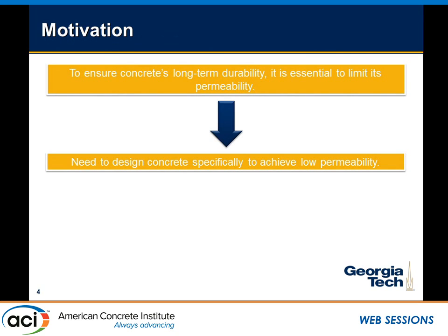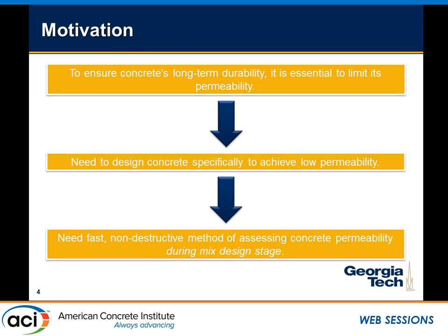Typically, at the mix design level, most of the tests that are commonly used take a while to do. Like a long-term diffusion test, for example, might take 90 or more days to conduct. And moreover, they provide just a snapshot of what's going on in the concrete. You're only looking at a particular age. What's more important is seeing how that changes over time. So we need a fast and non-destructive method of evaluating the permeability during the mix design stage itself. And that's why I'm focusing here on the surface resistivity test, because it's not only fast, but it's also non-destructive, which means that we can do the same measurements on the same samples over a particular time of interest.